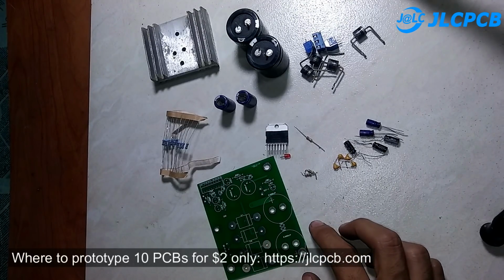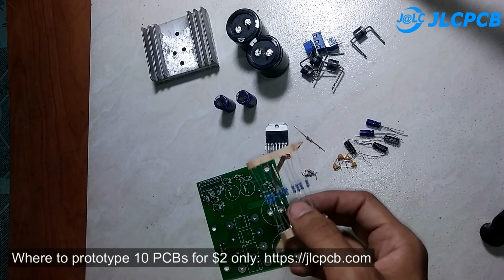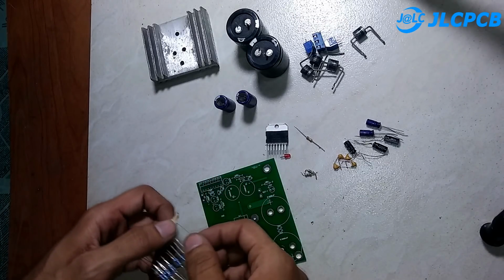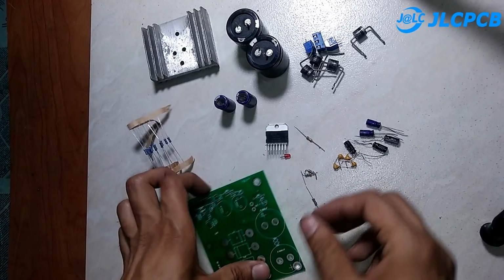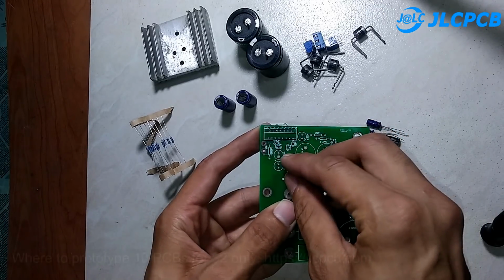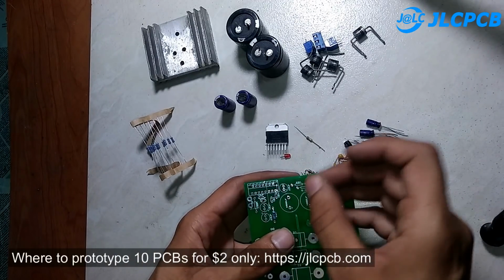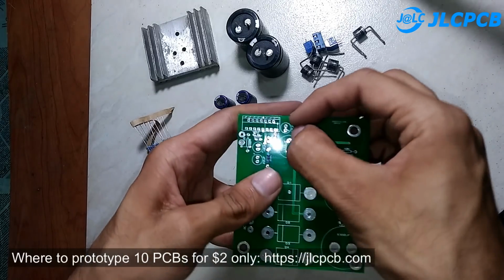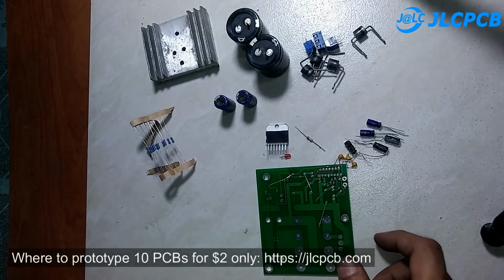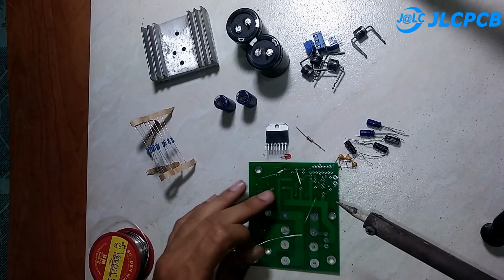So I'll start from the smaller components, means that I'll start from the resistors, and I will prefer to start from the 22 kilo ohm resistors. So guys, let's start. I'll just put this 22k resistor at its place and we'll solder it. Similarly this one. Now I'll just quickly solder these components to make the board ready to use.